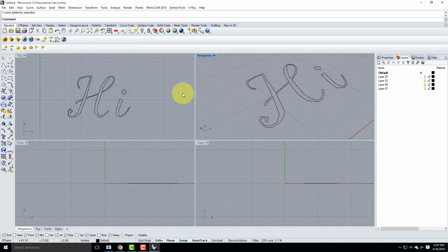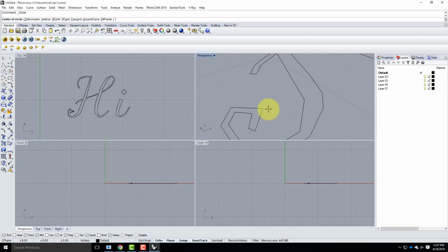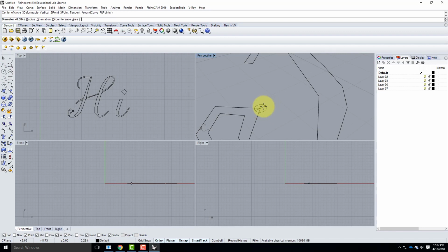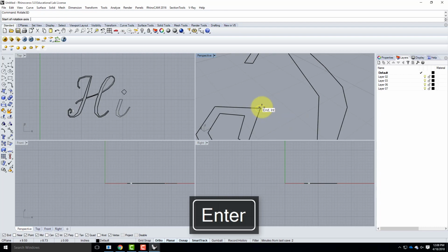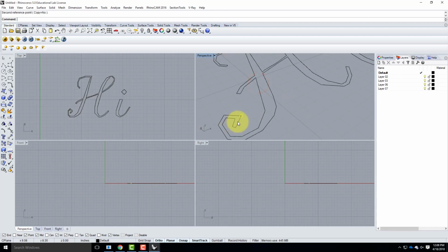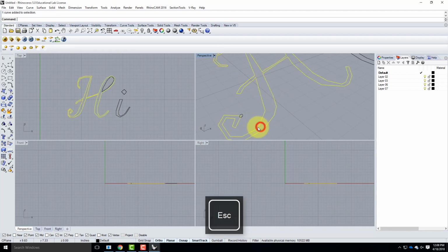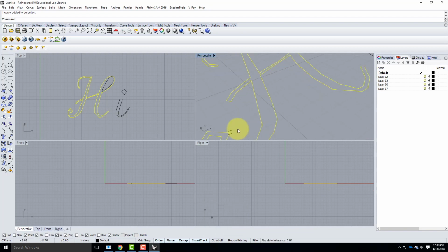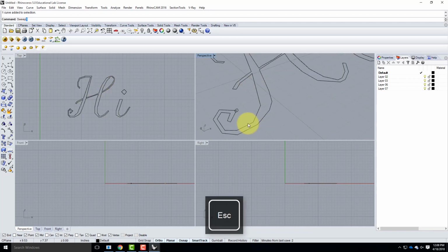All right, so what I need now is a cross-sectional curve. Essentially I'm creating the tube. So I'll go to one of these points, we'll start there, and I need to create the neon tube, whatever it is. So this would be the width of the tube. So maybe it's like that. I'm going to rotate 3D so that it's standing up on edge. And then I'm going to sweep across this curve. I may end up having to do this in a few passes to see how it works. I don't know yet. So let's do a sweep one.